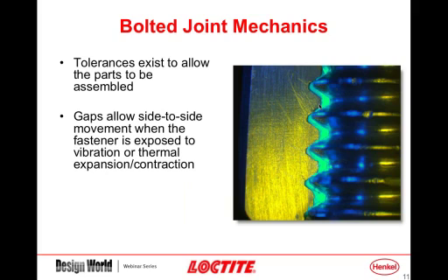This surface right here where the thread roots intersect is where you are driving the two ramps over each other. It's also where you're generating a lot of the friction, and it's this friction generated here which actually holds that fastener in position. Now there are other places where the friction is holding it together, but this is one key area. We're going to come back to this a little bit later.